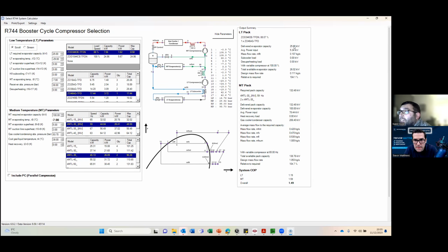if you look at the THR of the LT, it will be its evaporator capacity plus the power input. So that would become 30, plus any non-useful superheat, which will increase it up to the 32.48 that you see here. Plus, obviously, the non-useful superheat on the mass flow of this. So they're adding it all together. When you add it all together, your total cooling capacity of those compressors, which is different from connected load capacity, is 132.48.